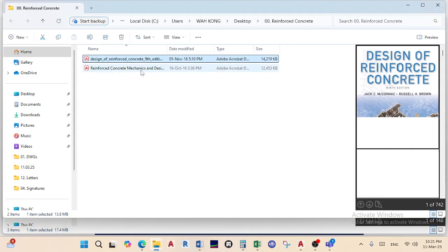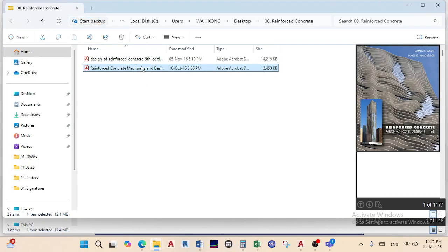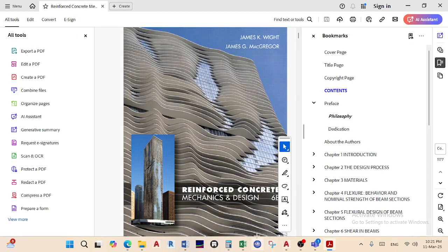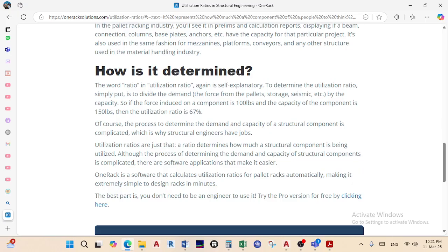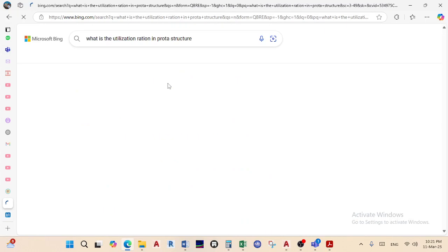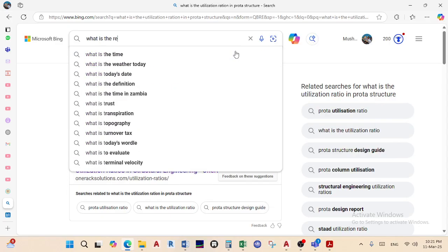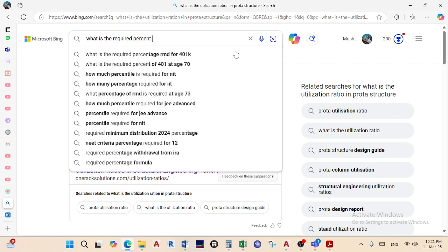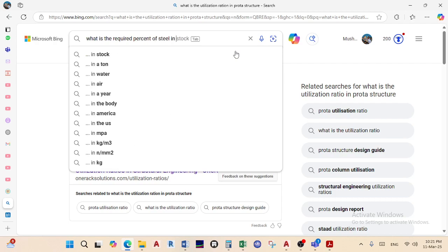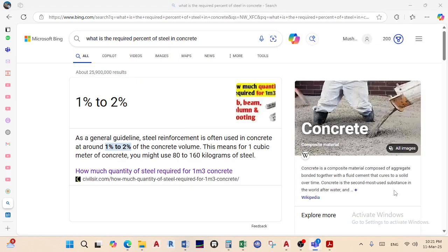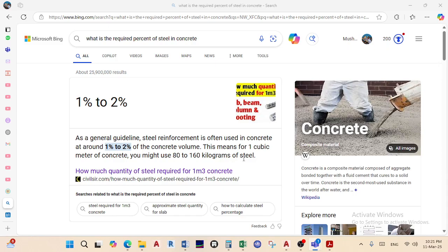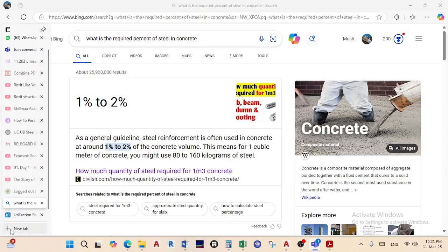Yeah, so looks like the percentage of reinforcement is around the same because we are using the same steel. So the applied steel in percentage is 1.17. But how does that affect the utilization ratio? It affects it differently. Some you find this, it's because of difference of loads. For some like this one, 4C124, 4C125, it's because of the type of load probably acting on that column, sorry, it's less compared to the load that the other one is carrying.